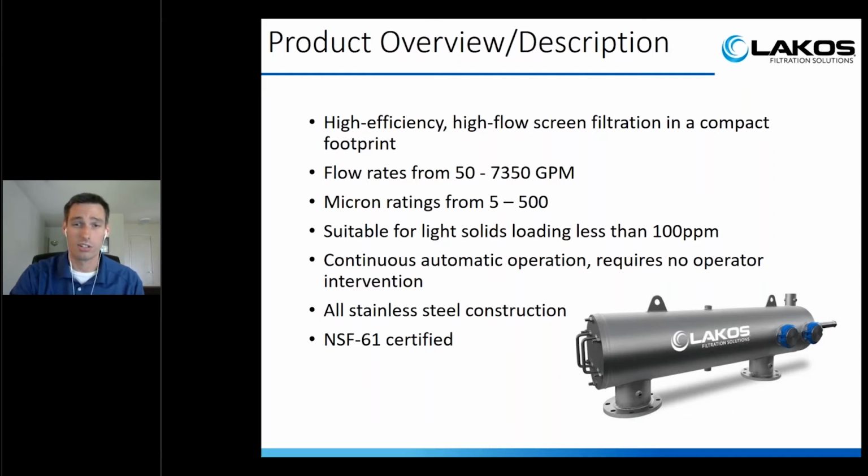It is all stainless steel construction. The housing is 304 stainless. The internal screen is 316 stainless. And if you have any applications where it needs to be drinking water safe, NSF 61 certifications do come with this. We can provide that documentation if you have customers that need it.